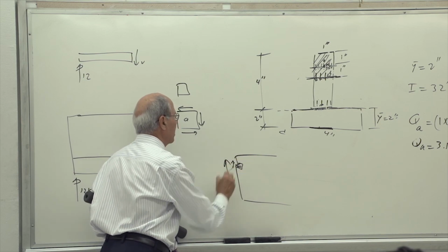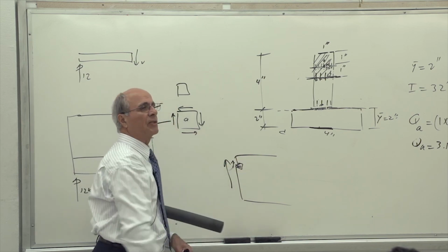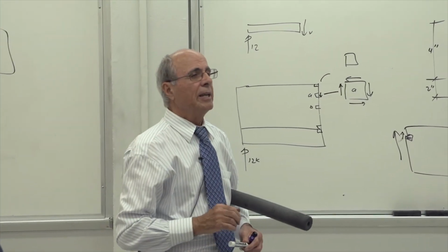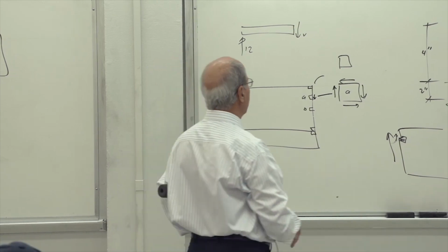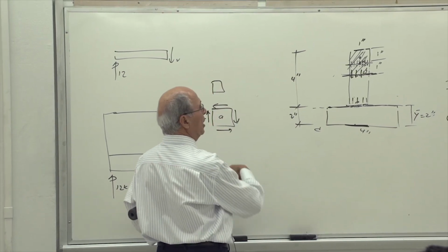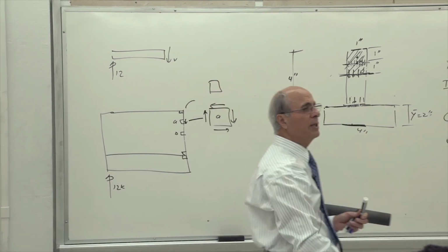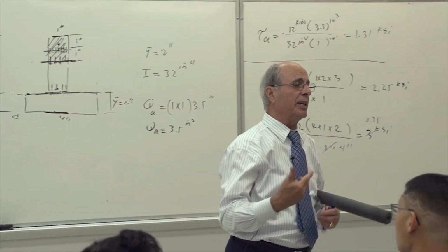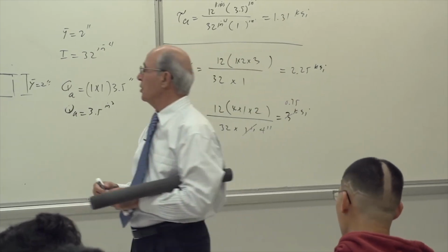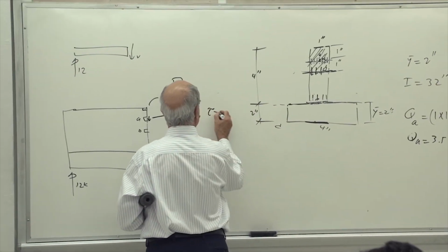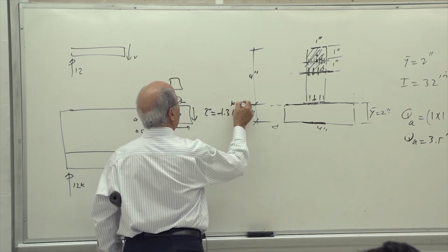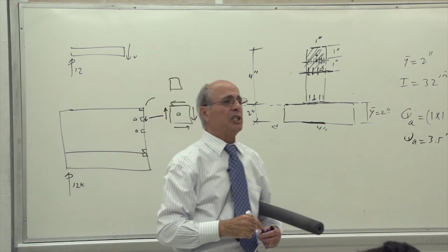So the shear stress will be like that. So we see this side versus that side. Is that correct? That means you can come from the right, you can come from the left. Is that understood? That does not make any difference. However, the shear stress for this one in magnitude is equal to how much? In magnitude is 1.31, but actually it is a negative. Yes or no? Because this is a negative format, correct? So if you want to go to chapter 7, please write it down. Tau equal to minus 1.1 KSI. And that is as far as the shear is concerned.